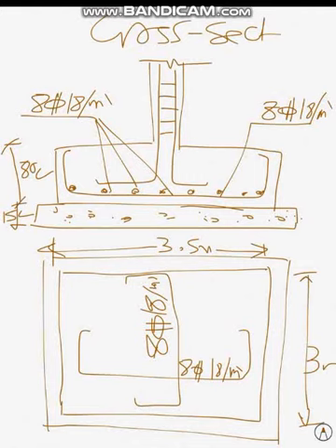The strip foundation, I will send you an example for it. It's so simple. It's the same way as we have already discussed here in the isolated footing, but you have to analyze one direction only, and the other direction we will put the secondary reinforcement by the minimum value only.